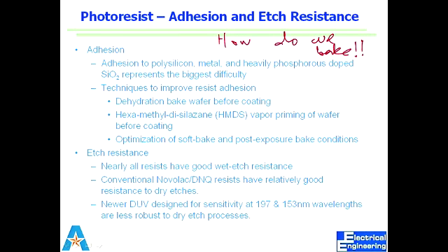Some plates have vacuum suction points, so you place your wafer and start the suction. Those vacuum ports hold the wafer down and keep it in very close contact with the hot plate. That's one way we do it.